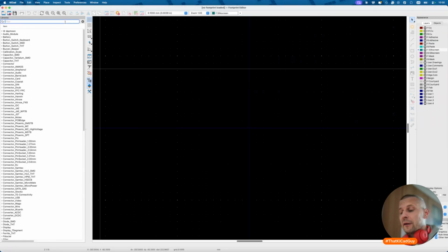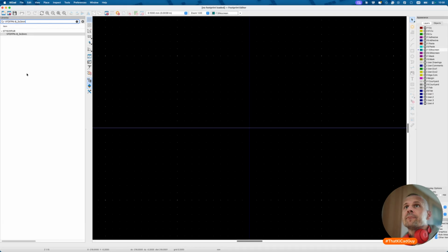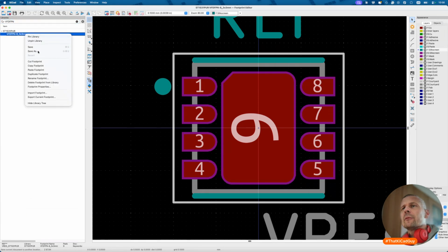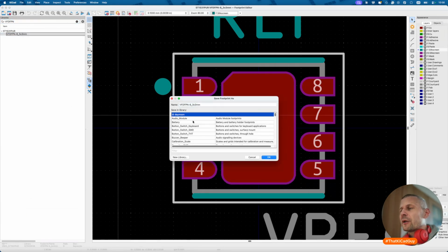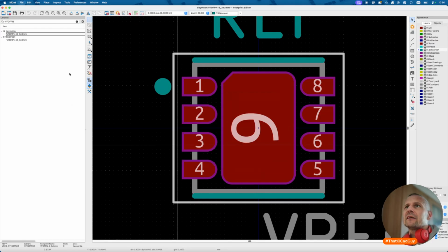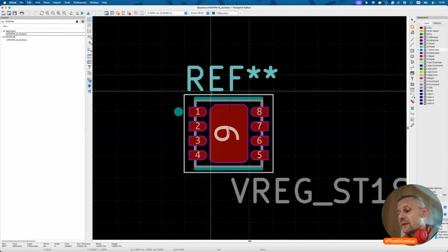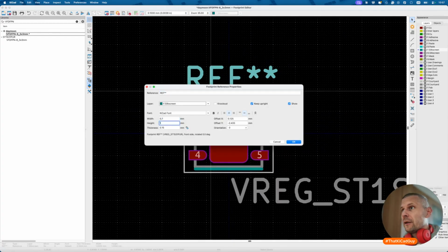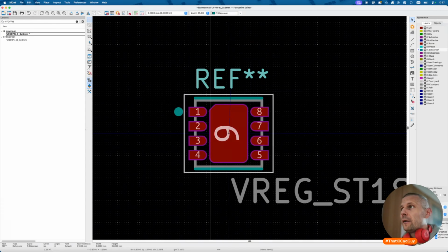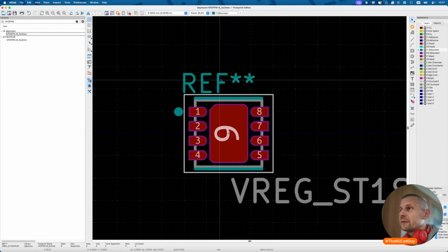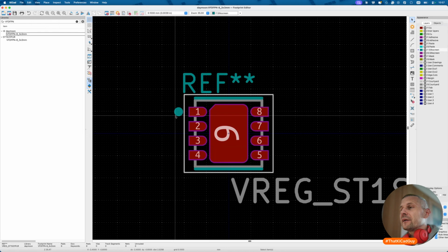The footprint, I have it in my clipboard here. Yes, this is it. And just for the sake of it, there's no similar package in the footprint library of KiCad. It means that I am not going to duplicate this, which is something I really don't want to. Yeah, 0.8 is like the minimal size, well readable. 0.7 is good as well, but I will keep it.